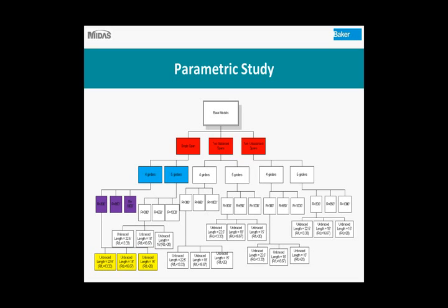And you should also note, if you look at this diagram, those 3 different unbraced lengths only applied to the bridges with the 300-foot radius. The other bridges that had a radius of 650 feet and 1,000 feet, their cross-frame spacing was controlled by the maximum that was allowed in the code. So those were set at 25. But for the 300-foot radius, we had those 3 different options that we looked at.